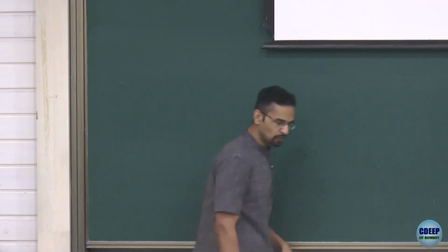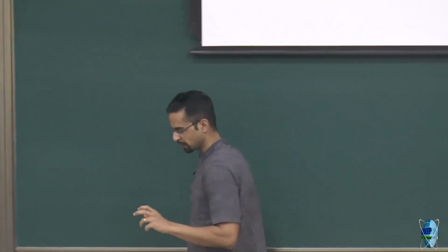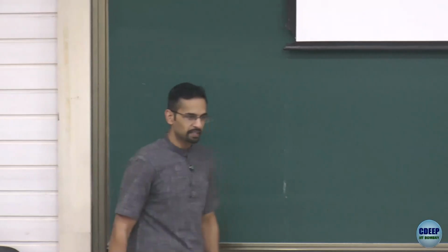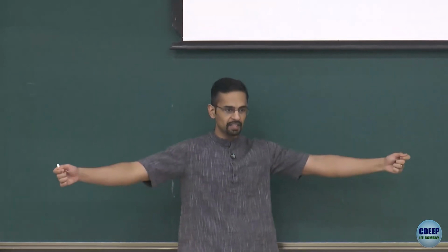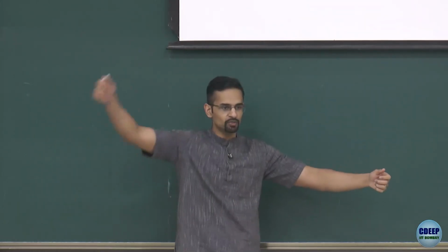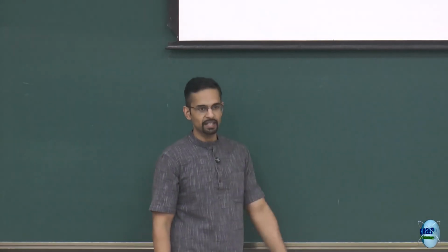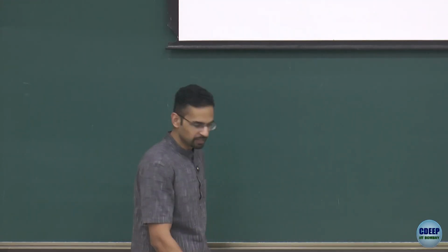Okay, so the first thing we look at is, we have been talking about velocity differences and how they vary from large scales to small scales. But because I have a velocity and a certain length scale, I will have a time scale associated with that eddy. So large eddies you expect to turn slower, small eddies will maybe turn more rapidly. But how exactly will this vary? That again, in the inertial range, will have a nice Kolmogorov behavior. So let us see what that is.